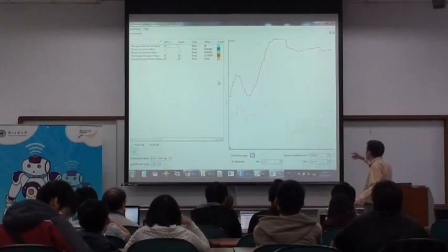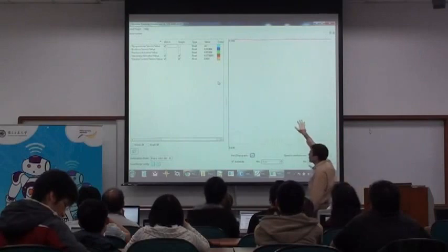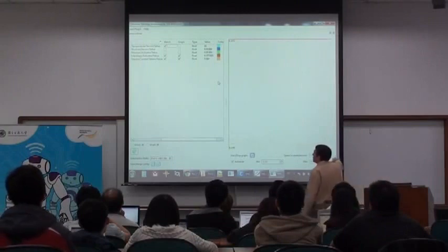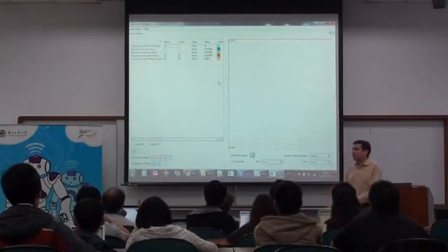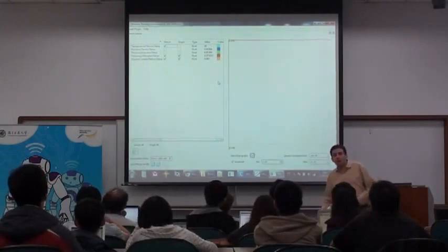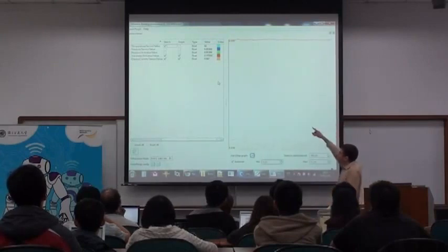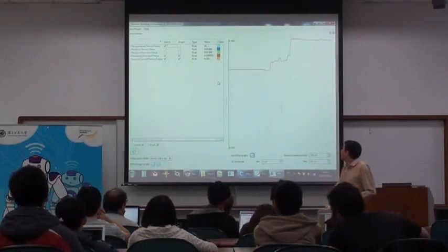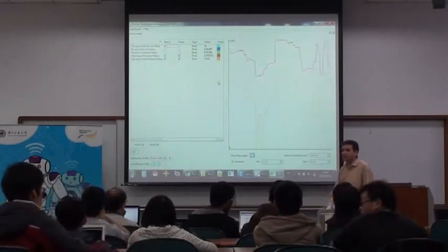And in red, you have hardness or stiffness, which is the same, currently around 0.3. And in yellow, you have the electric current, which is quite low. Why? Because the robot doesn't need to send some current to the motor to keep this position. But if I force on the joint, on the articulation, you will see that the stiffness will increase and the current will also increase. You can force it gently on it, and of course the robot is sending more current to try to resist this.